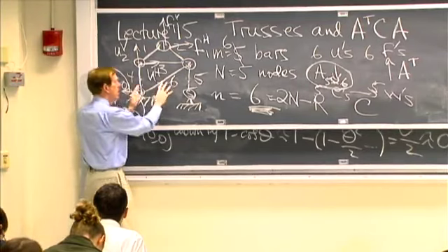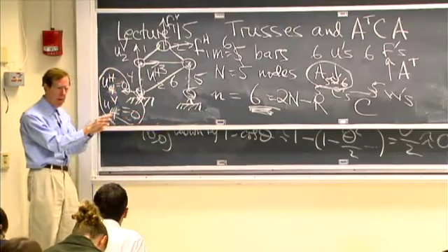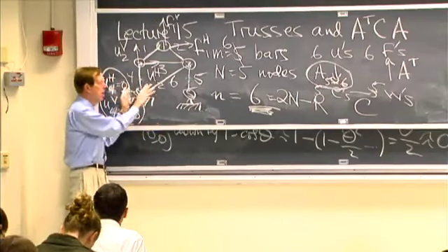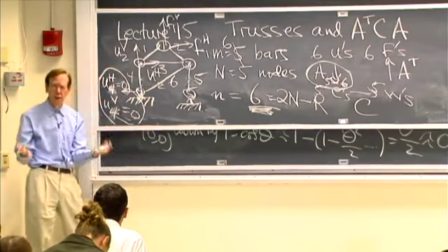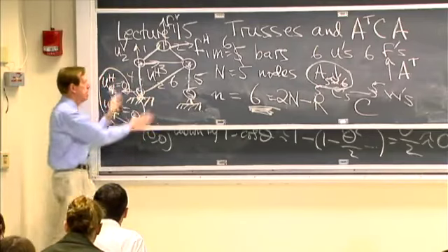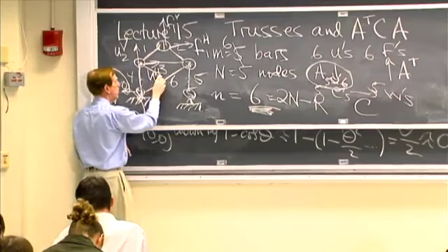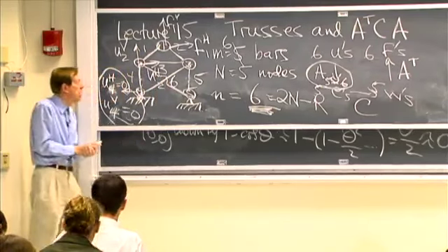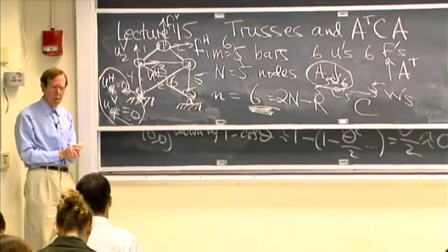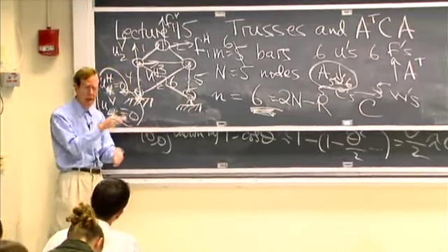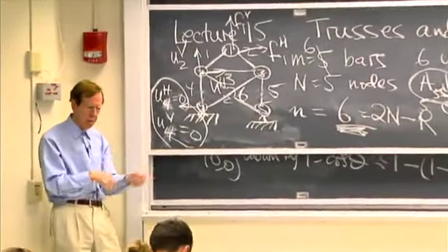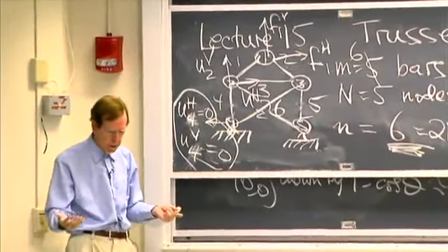I haven't written down the matrix, but I'm really calling for engineering intuition here, that this truss is now stable. And of course, I can make it even more stable by adding a 7th edge, a 7th bar. When it was 6, I had square matrices: A transpose and then C and then A would have been square.